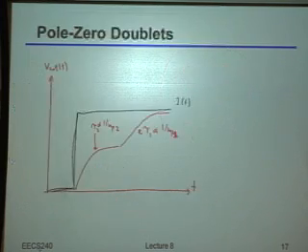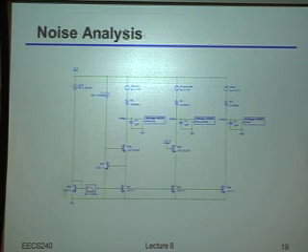Okay, great. If not, let's go ahead and discuss one last quick thing with respect to these current sources. So far, I said we can play these cascode tricks. It's really nice. It works very well. It gives you higher output impedance. But the next question you may ask yourself is, do I have to pay anything for it, other than, of course, the Vmin? In particular, do I have to pay anything for it from a noise standpoint? It turns out there's actually some very interesting phenomena that happen here, specifically in terms of the noise performance of these types of structures.